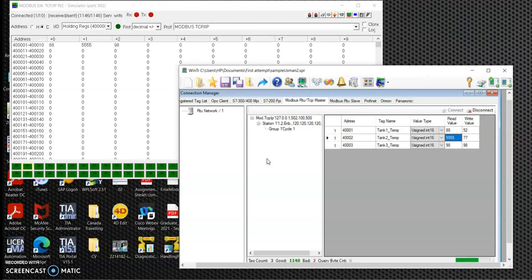Unfortunately, we don't have the PLC, so what we have tried to do is use a simulator instead of a PLC. And the values that will be thrown out from the PLC command, like sending into the register and reading it, you can just read with the register address, and you have to define the tag with the same address, right? So it's going to pick the same value, and the operator would now sit on the screen with his design screen. He would just write 72 or 82 and it will eventually go to the PLC and eventually into the process control, right?